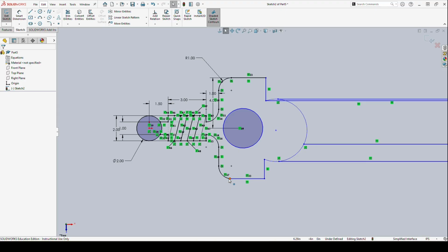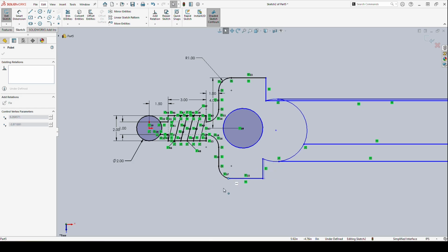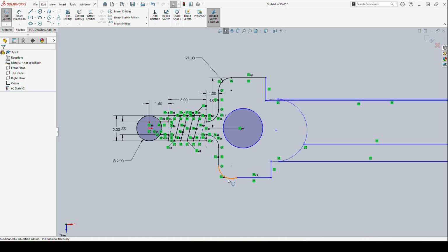Next thing we're seeing here is I have, as you can see at this point, already added an equal dimension. Oops, writing over it a little bit there, to this top and this bottom curve. However, this bottom curve can still move. Remembering the equal dimension for a line says that the line has equal length. For a curve, it is saying it has equal radius.